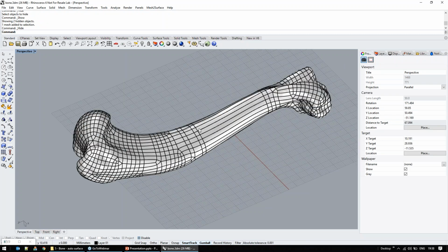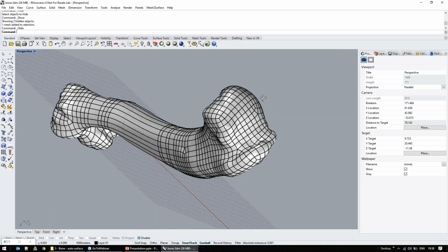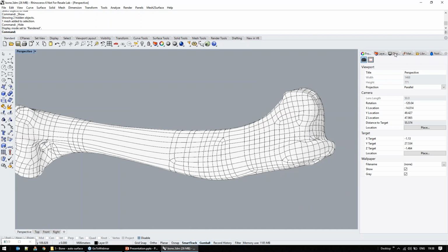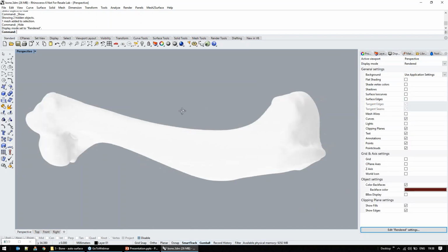As you see, the software has tried to optimize, and it doesn't create a surface for every face, but it tries to build all the neighboring faces into a single patch. And this is a valid NURBS surface which can be trimmed, exported into IGS or STEP format, or processed for any other needs.